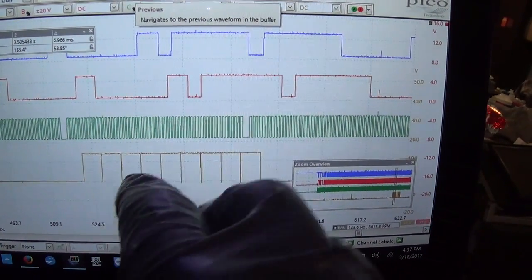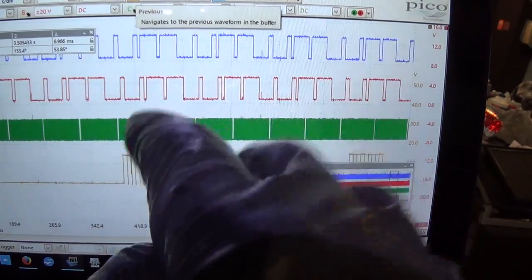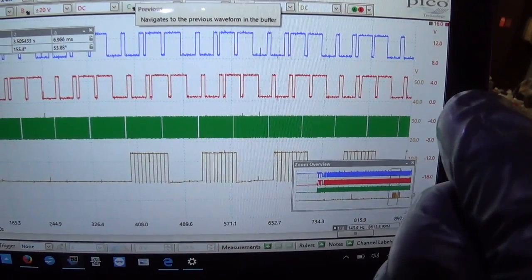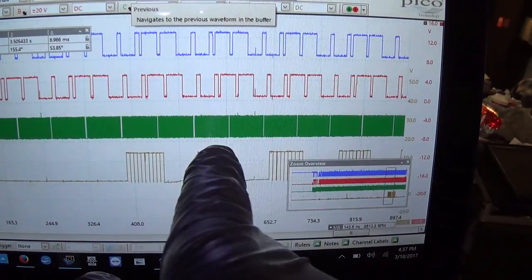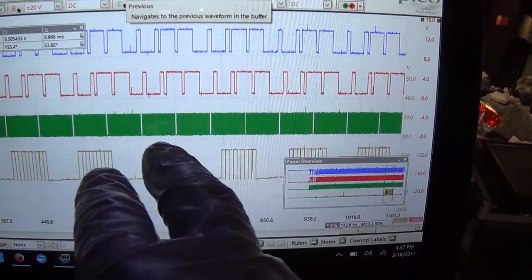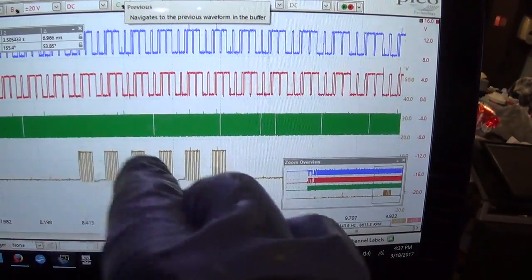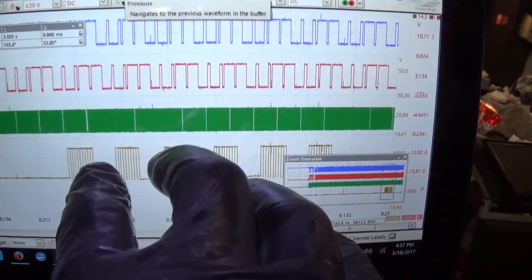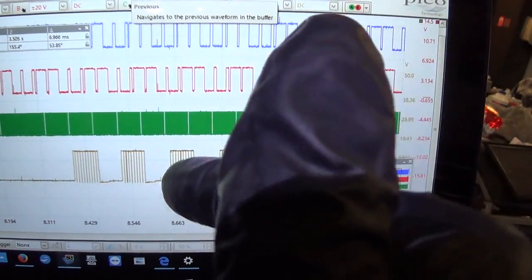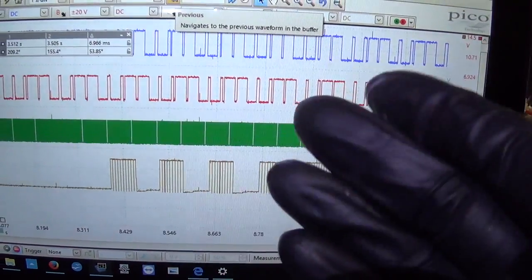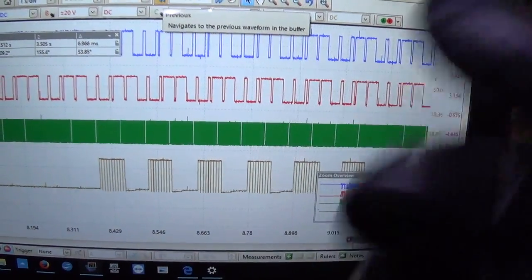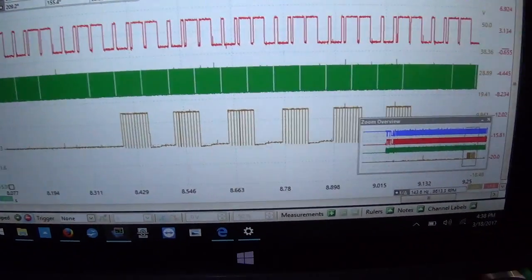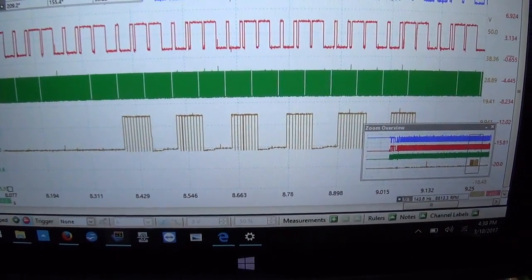I want to measure the resistance of this intake solenoid because we have a known resistance spec. The neighbor next to it, we can compare to that just for reference and see what the heck this is all about. I don't know if this is a known good test sequence, or if the solenoid's shorted or something. Maybe it's trying to limit the current. But this solenoid was just recently replaced in attempts to fix this problem, and nothing changed apparently. Now it's not an OEM solenoid, so again, let's do the resistance check just to be sure and see what this waveform is all about.